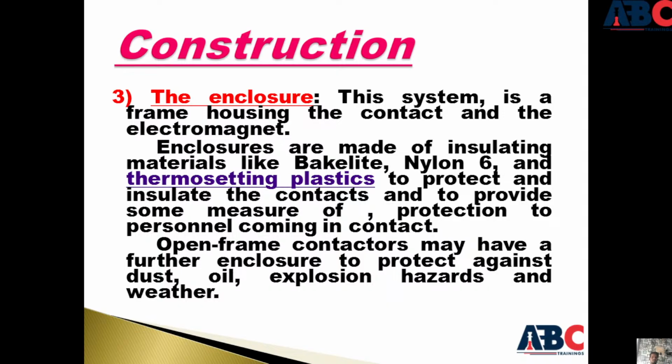Enclosures are made of insulating material like bakelite, nylon 6, and thermosetting plastic to protect and insulate the contacts and to provide some measure of protection to personnel coming in contact. Open frame contactors may have a further enclosure to protect against dust, oil, and explosion hazard.